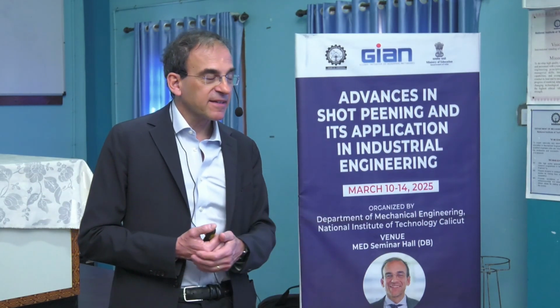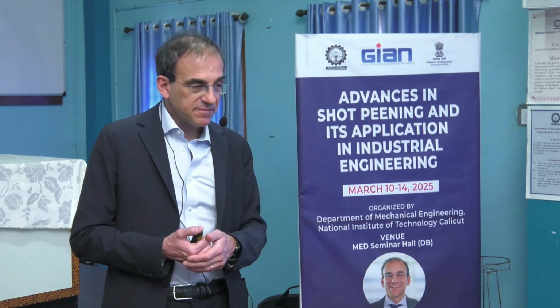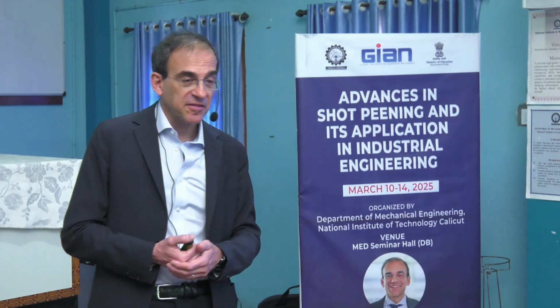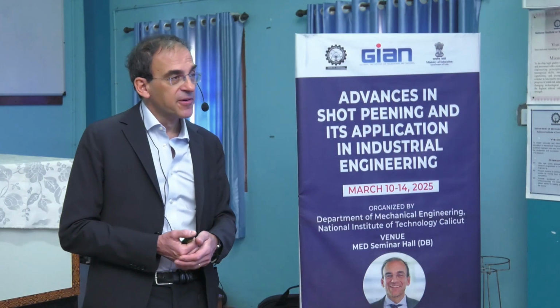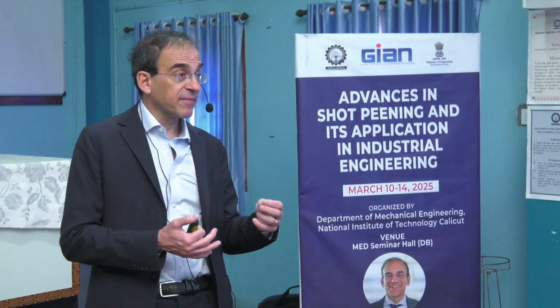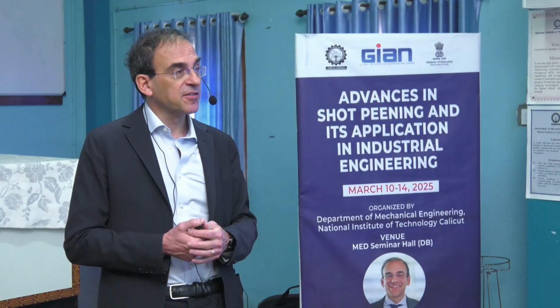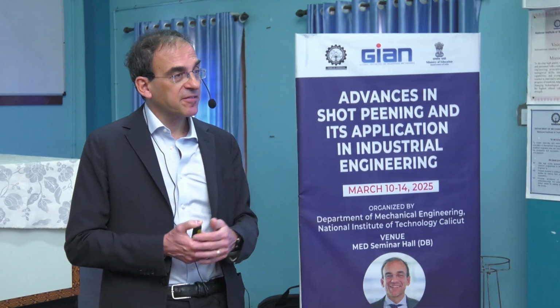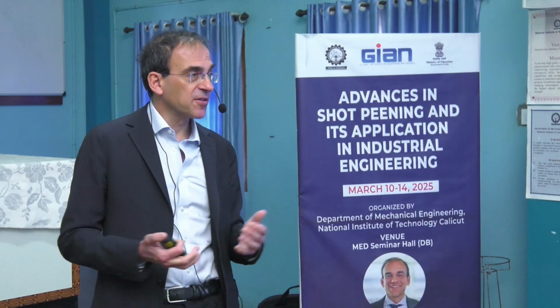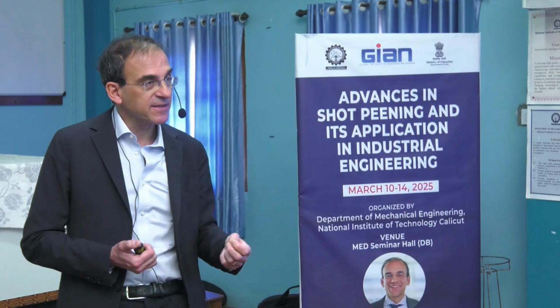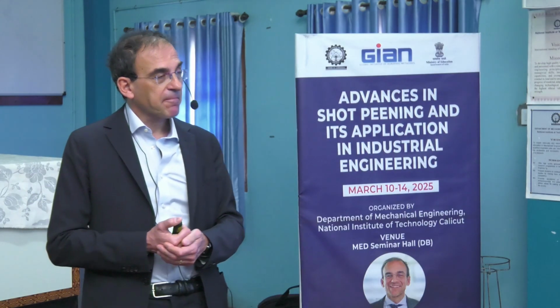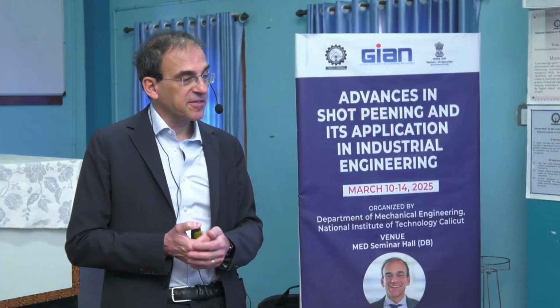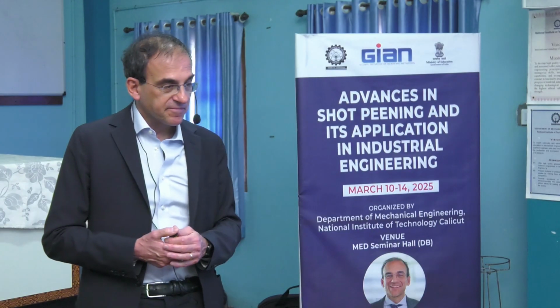One attractive method, both for the accuracy and because it is not destructive, is X-ray diffraction. It is widely used, but it's not the only one. We can also use the hole drilling method, and some other methods that are commonly used for this kind of measurement.